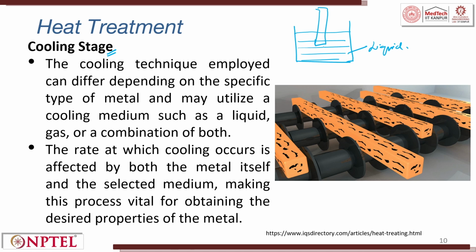When we quench the material, it can be a sudden cooling. If you have an oil, the cooling rate will be much lower. So, you can also blow air and then cool it. So, you can think of liquid, you can think of gas, or you can think of something like steam also, depending upon your application.